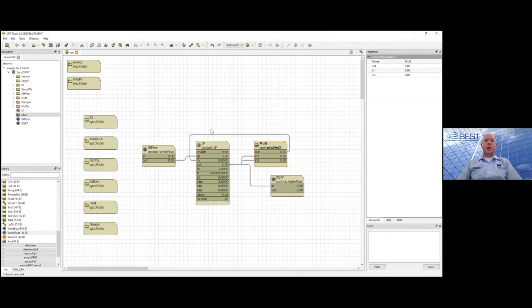As soon as we drop a value in, with differential pressures, we're looking at small numbers here. We're looking at, at most, an inch of differential pressure, which is a huge quantity of airflow in most situations. Even if we're looking at half an inch, if you enter it the correct way, our loop will cycle through.